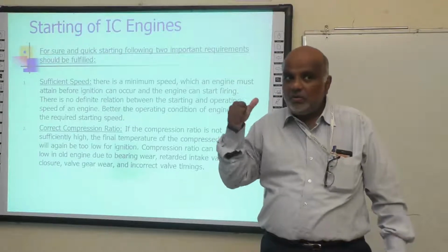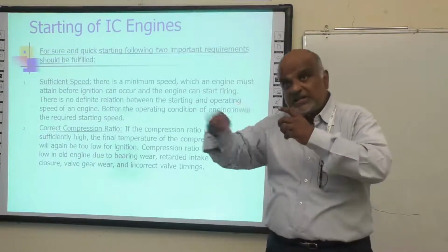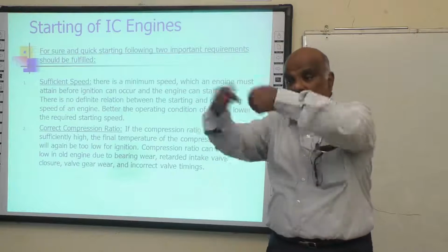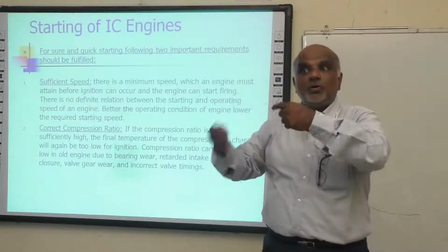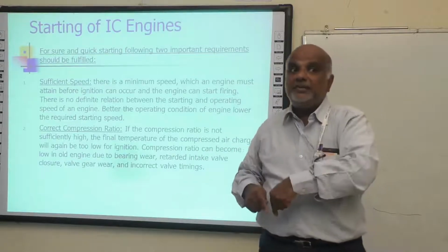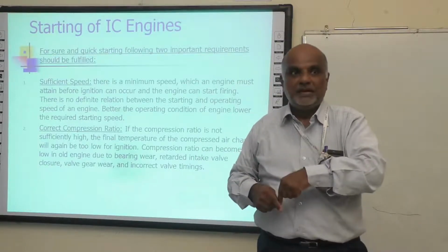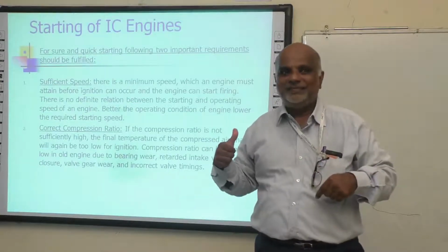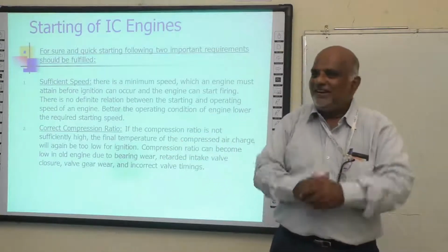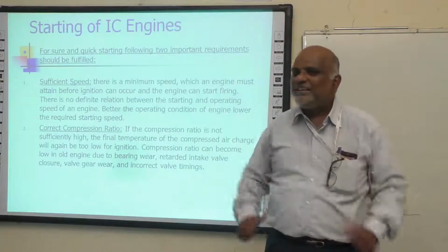If you don't take it off, what happens is the engine is started with fuel, and you are also giving battery power, so the engine RPM will be higher. It will overtake the battery power, and you will damage the starting system. Self motor, you will damage the self motor. So you have to take your hand off at the right time. It's made much more comfortable and easier for us nowadays.